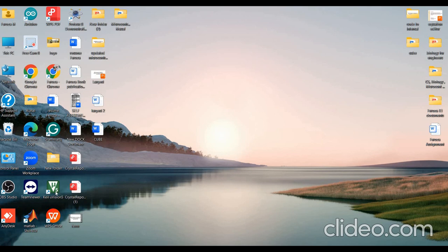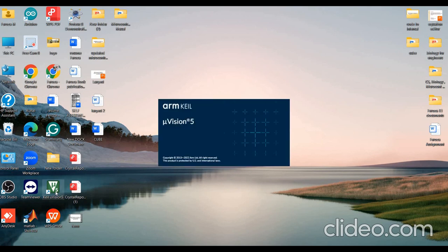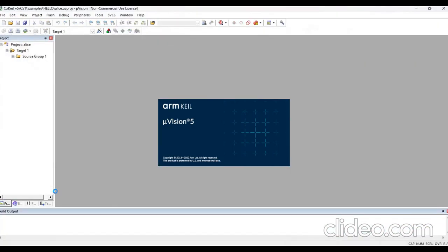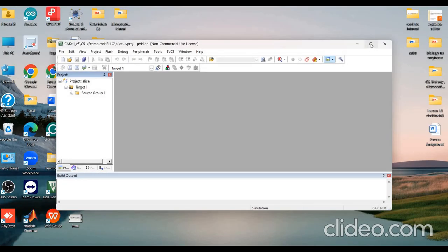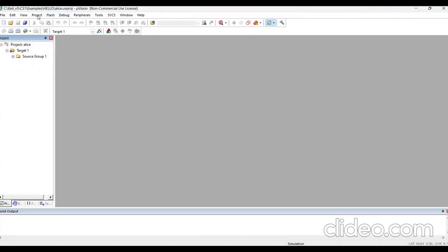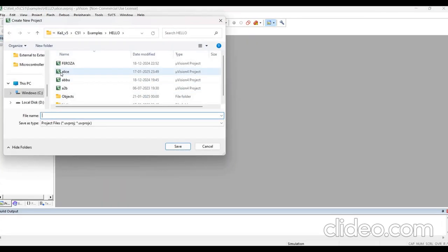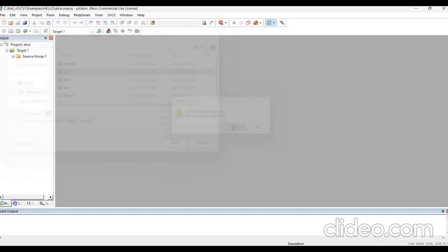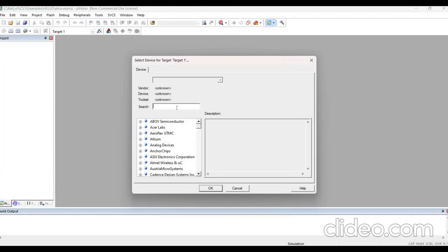Now we'll execute the program. We'll open the Keil software. Maximize it. Go to Project, New uVision Project. Select the name of the project. I'll use the previously used project. I'll click on yes. Then search for the device, Microchip.